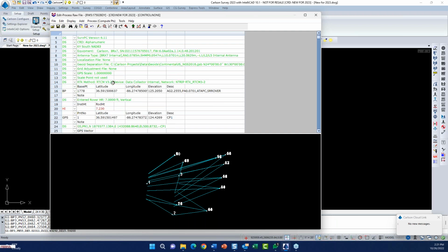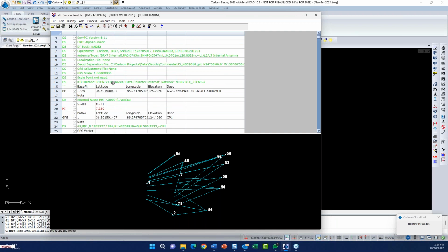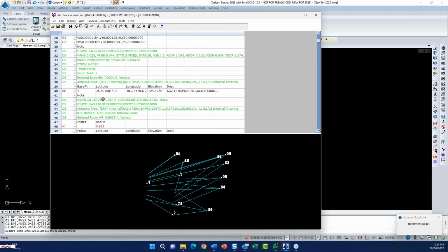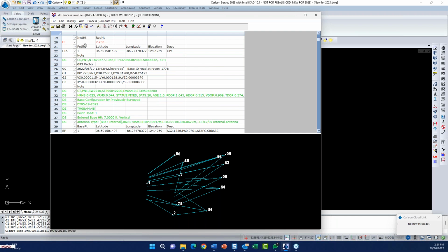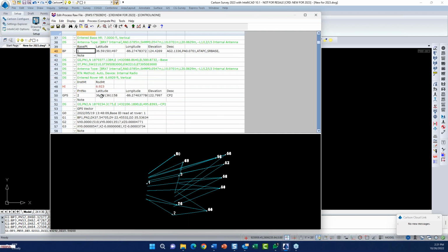Another upgrade, in addition, is, so here's the idea. This is a GPS file, and they had a base point, their originated base point, and I don't know if they located everything from that base point. Now they located point number 1, and then they moved their base point to point number 1 and began locating other points around here.